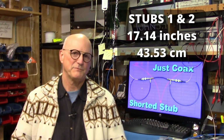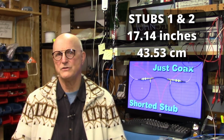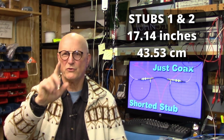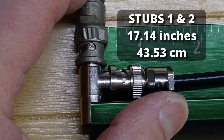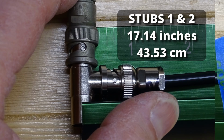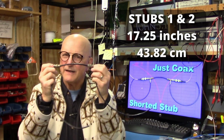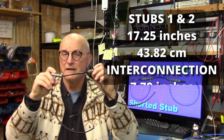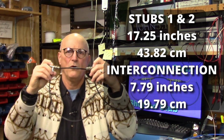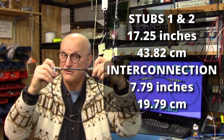Now, to allow for the whole shorting thing, I will add the radius of the coax to these lengths. And in this case, because my coax is 0.25 inches in diameter, this is another 1/8 of an inch or 3.2 millimeters. I'll explain my method of shorting the ends when I get to the construction in just a little bit. So I will cut both stubs so that the entire assembly, including the BNC T, is about 17 1/4 inches or 43.815 centimeters. Now, the interconnecting coax isn't as critical, so I will cut and terminate it so that the overall assembly is the calculated length of 7.79 inches or 19.79 centimeters, including the BNC Ts, which will be installed at the ends.